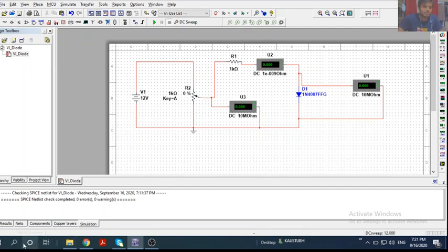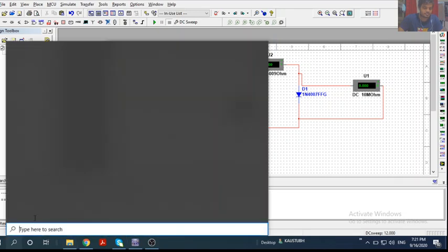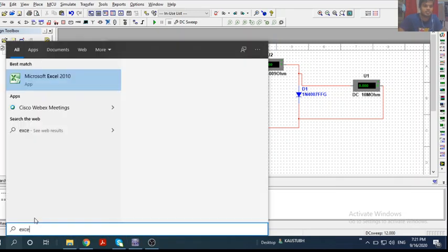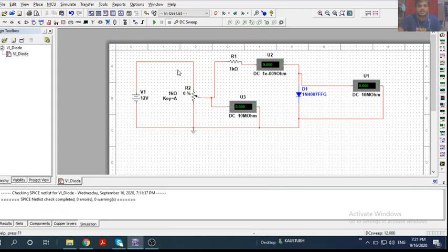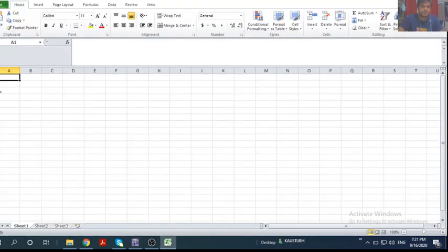Okay, let me do one thing. I'll open an Excel sheet where I'll put the values. Okay, that is how we do in the lab, actually in practice, physical lab. So this way we connect. Actually in multimeter we connect here in the lab. Here actually I am connecting the ammeter and voltmeter. Okay, so what I will do here is cell number, then applied voltage, let me put it as Vs, source voltage. Here I will put Vd, voltage across the diode, and here current through the diode.